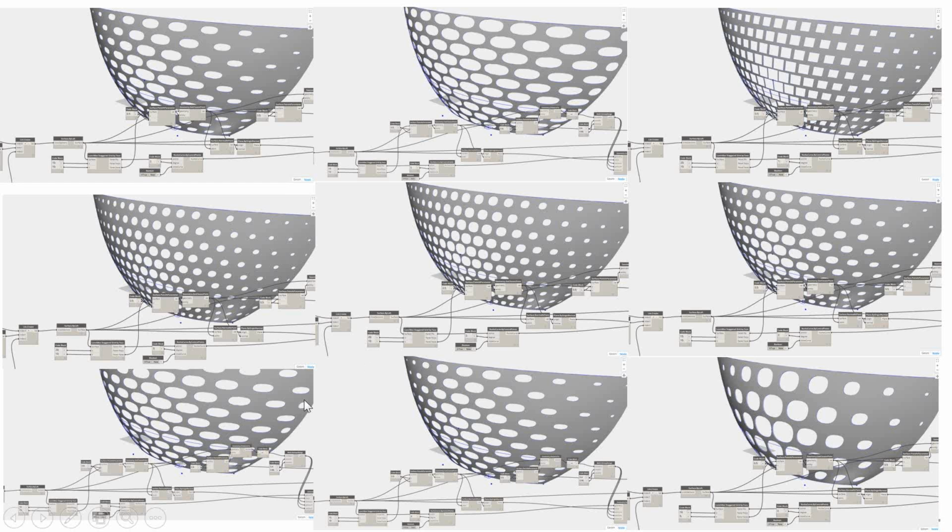And we'll talk about that a little bit more. Once you have these things, because you're designing a system, you can change that really quickly. So you can do options, you can look at variations really easily. In this case, this is like a facade screen, just looking at different perforations in a metal panel, for example. You can run through that simply by changing a slider or some input and not have to worry about remodeling anything. And it's a lot more flexible than simply building up a parametric object in Revit, because you can change things at a higher order, and Revit's not going to yell at you. It's not going to fail because something isn't there. It just is simply getting rebuilt from scratch.